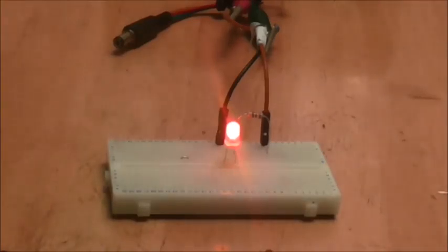The forward resistor is in there to stop the LED blowing itself up. What will happen is that if you put the LED to positive without a resistor, and then at the other end negative, it will draw as much current as the supply can handle, and it will very, very quickly burn itself out. That is the only reason we need a forward resistor, and in fact, under certain circumstances, if you're using 3 volts and a 5mm LED, you can get away without a forward resistor, though it's not a recommended practice. Well, having said that, we've seen a red LED. Let's have a look at a few other colours.